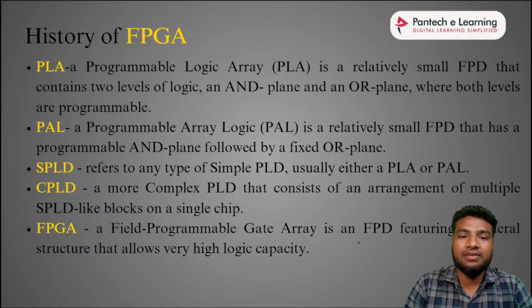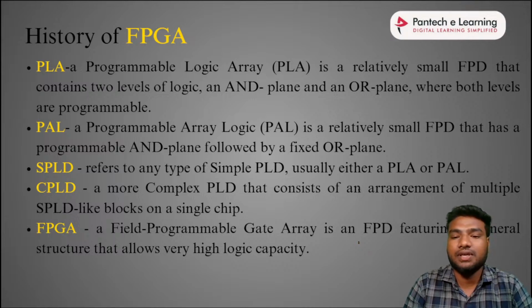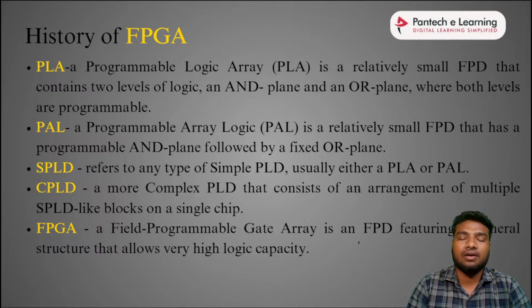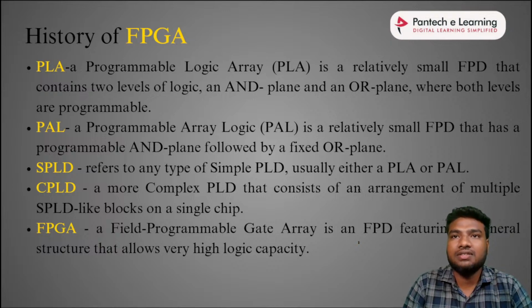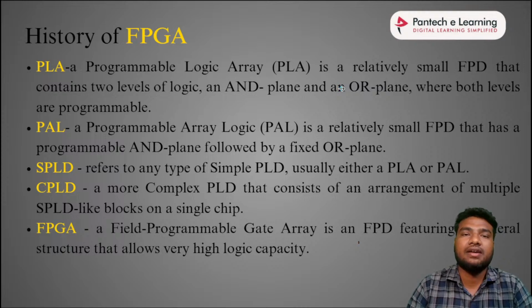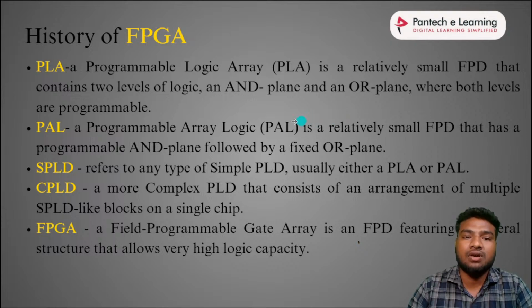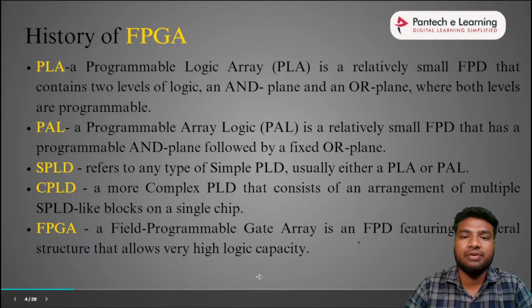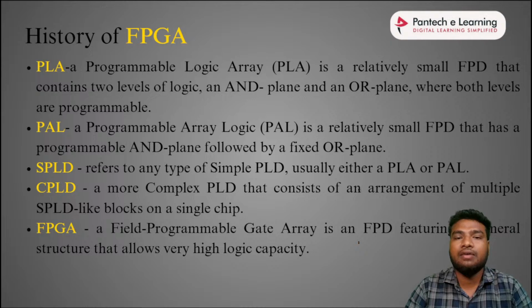This form of architecture we can program. It's like an FPGA model, and finally we come to the FPGA. It has n number of logic capacities, so we can write n number of logics inside the FPGA. If you write some accelerator logic using AND or OR planes, it is a very huge task to write the logic and to assign the logical elements. In the FPGA we have the mux, lookup table, and flip flops, so we can achieve all kinds of digital circuits.